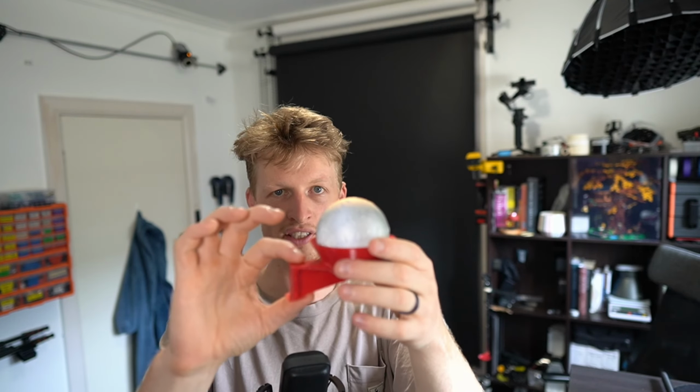Now, this is something that we've talked about a fair bit on this channel: how can we know if the ball is actually in the hand? There have been various suggestions, like pressure sensors, and sensing with the hand motor, because the hand motor is sensitive enough. If I have it turned on and I'm viewing its position, velocity, acceleration, current in real time, I can see, even if I very gently put the ball in the hand, the hand motor is sensitive enough to detect that weight.